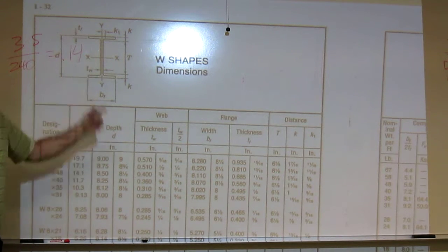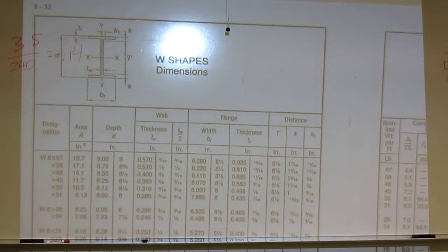By the way, if you need to draw this end view, you can get all the information right here. There's another way to do it. Type STL after you've loaded your AutoLISP program and choose the beam you want. It'll draw it for you. Depending on which way you're looking at it, even if you want a 3D model of it, don't forget that. It's going to come in handy.